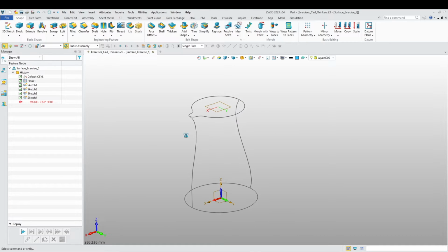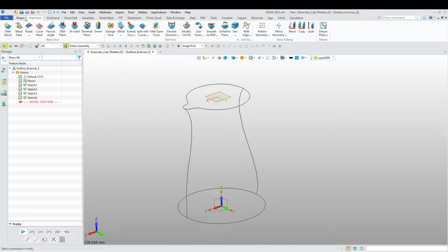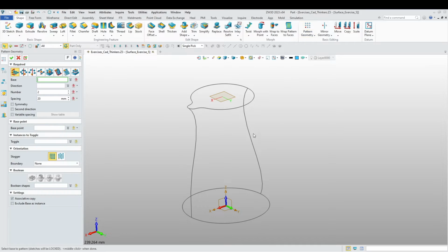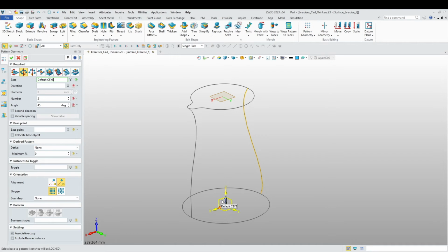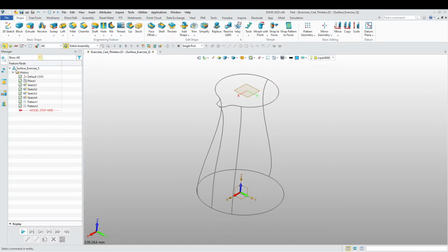All right. Excuse me. And there we have it. Now we can start with our first surface. So I'm going to go to Revolve. Actually, before I do the Revolve, I just want to do pattern, and I want to do Revolve pattern. Direction will be this one, and I want it to go 150 degrees. Again, direction is going to be minus 150 degrees. There we have it.